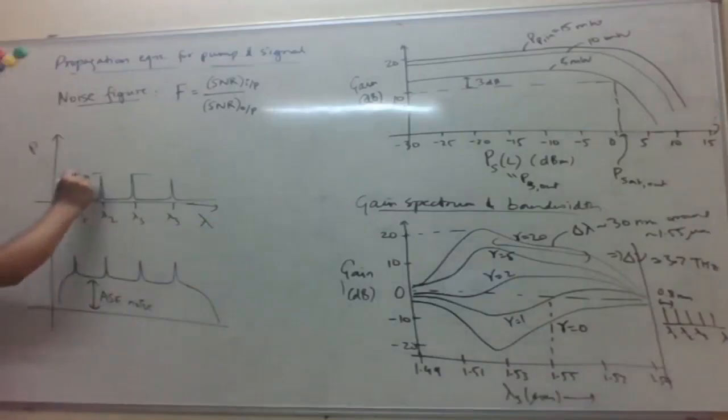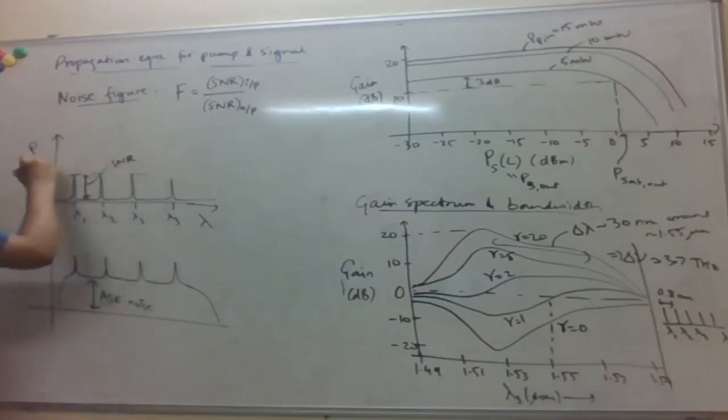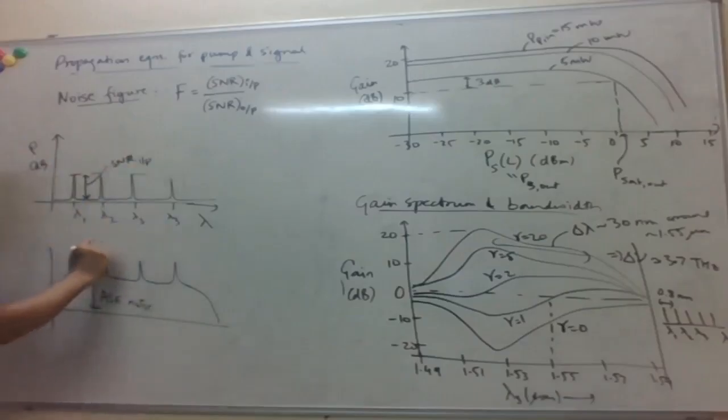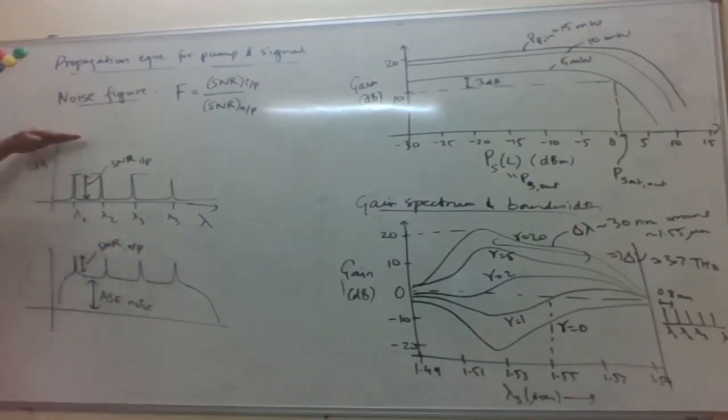Right, so this is the signal to noise ratio. This is the signal level and the noise level is here. So if this is in dB, then this difference here is the signal to noise ratio of the input, and here now you have the signal to noise ratio of the output. Okay, so this would be smaller than this, although the peak level has increased, right?